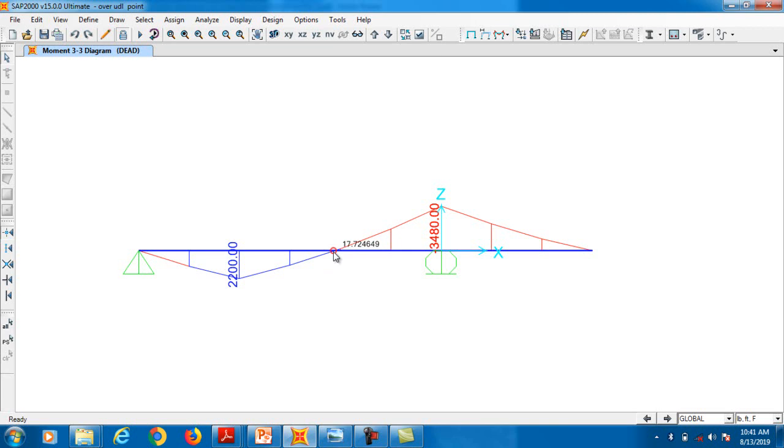It is necessary because if you are doing your RCC designing and you are finding out the distances of curtailment, like bending bars, cut-off bars, in those cases you need development length. So where we basically need to look at the point of inflection. For that purpose, if you are doing it manually, it is a very difficult job. You will make some kind of equations to find out this distance. So if you know about this calculation, you can easily find it out.